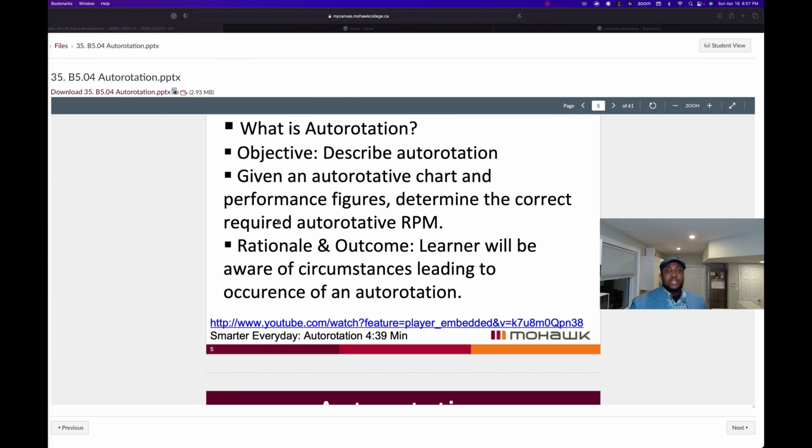Should ground resonance occur, however, the way that we recover from this is quite simple and effective. You raise the collective and apply power. Once again, you raise the collective and apply power. This breaks the cycle of vibrations bouncing from the top of the helicopter, bouncing off to the bottom and accumulating over time. So the way that we recover is you raise the collective. This will change the pitch of all the blades, increasing the pitch, creating lift, essentially helping you break contact with the ground and terminate this effect.